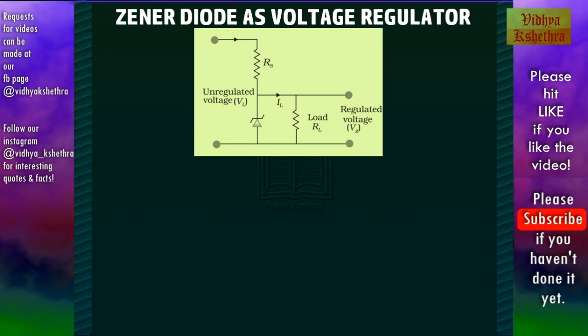Now we can see the Zener diode as a voltage regulator. The circuit is as shown in this figure. It consists of RS and the load resistor, which is in parallel to the Zener diode, while RS is in series.